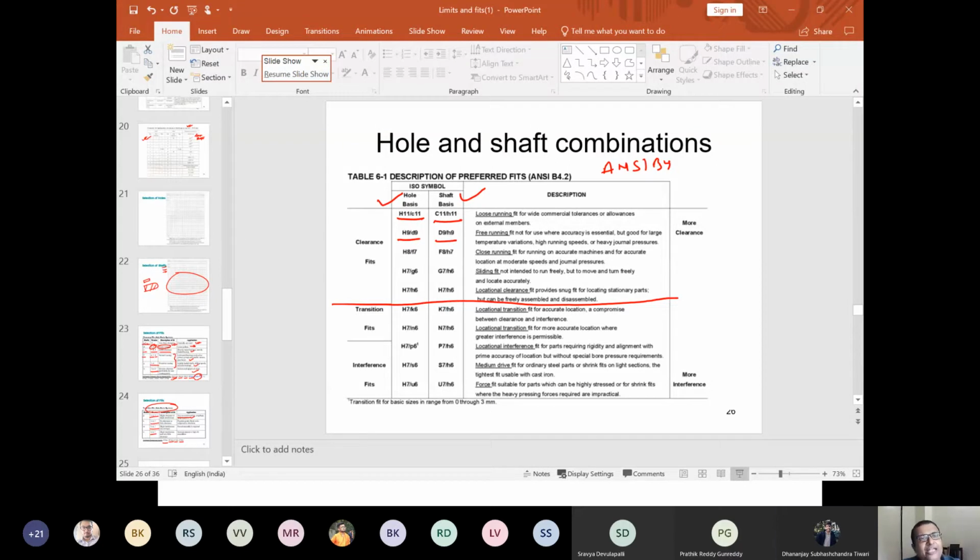So data has been fit in a way that if you plug in D, you get those tolerances in microns. You get me? But if it is ever possible to understand the physics behind it... First thing is it's not a physics thing. They have data, right? They know it's an experiential thing that for this shaft I need this much tolerance, and the tolerances will always be a function of your size. And you need standards. You cannot have different standards for different sizes, right?